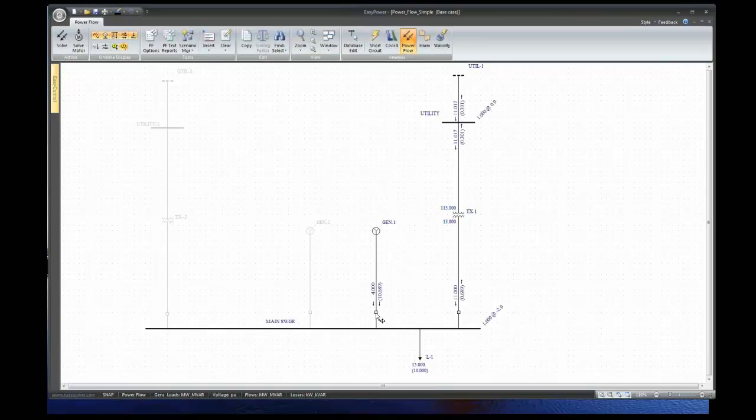So in Power Flow, we can use our smart breaker feature. If I double click on this breaker, it's going to open. And now you can see all the power is being supplied by the grid, right? So I have my load here being supplied, but look at my voltage. It's 96.3%.